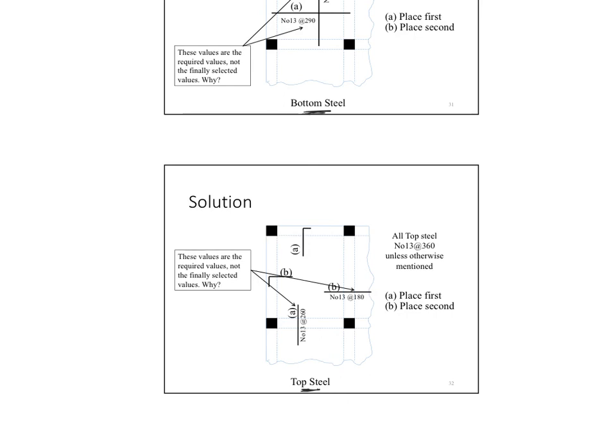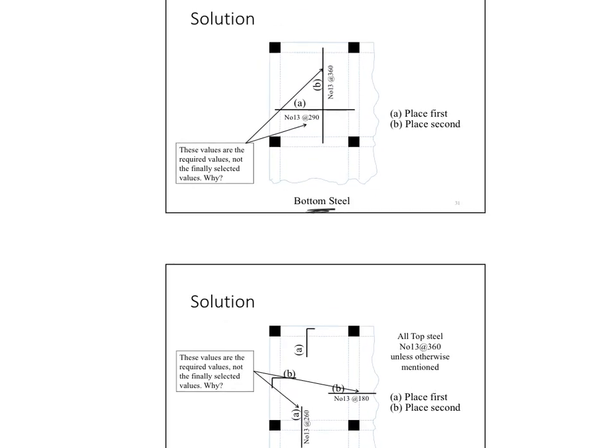Now the top steel, remember, will be placed at locations of negative moments. So they are above the beams, which are the supports. And the bottom steel is laid out between the 2 supports, so it's laid out from this support all the way to this support. Again, we place this one first in construction, and then we place this one. So we ensure that the D that is specified in our design is the same.